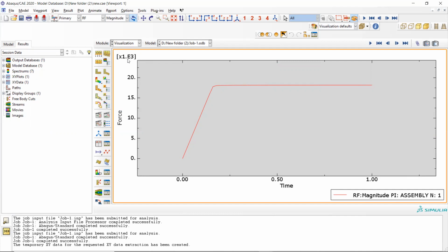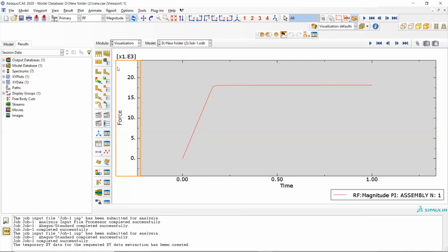Sir, every time we have to go with this displacement only, why can't we apply the load directly? Yeah, that's where, when you are solving F equal to K into x, for some of the problems, matrix division is quite comfortable, so it will solve and give it to you. But in some of the cases, matrix division is a big challenge for this kind of profiles. So in those cases, you have to go for matrix multiplication.